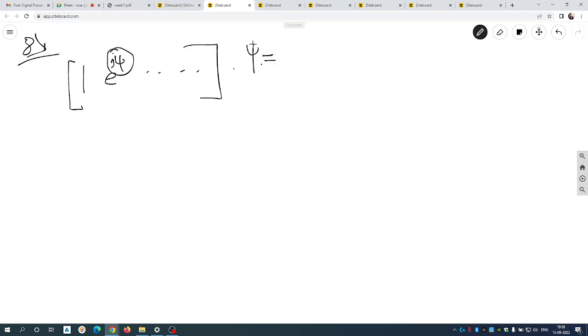For the receiver side, I denote it by R, and the lth number, like this is one up to L, L number of antennas are there. So it will be dependent on 2 pi by lambda, d cos theta, and it becomes e to the power j phi 1, e to the power L j phi 1.